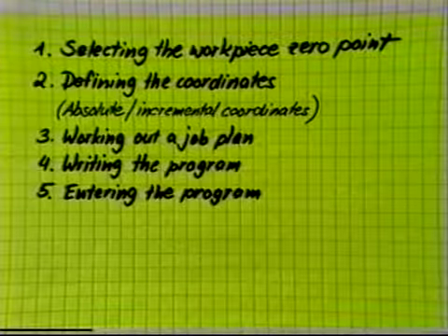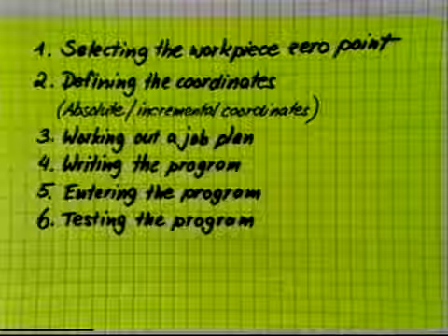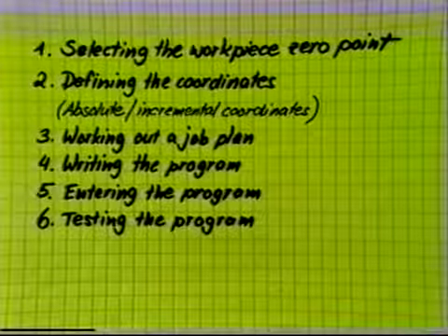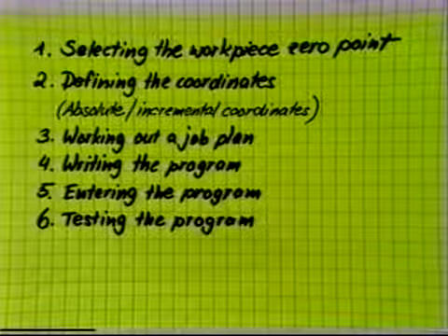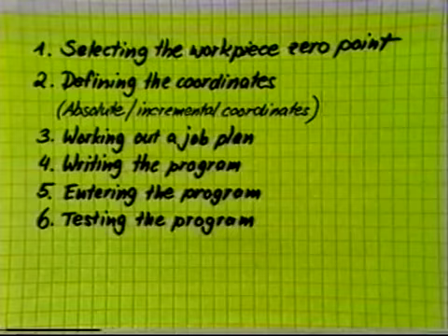Step 6, testing the program. Before running the program, you should test it first, just to play it safe. There are several ways of doing this. For example, doing a test run without the tool, doing a graphic simulation on the video screen, or processing individual blocks.